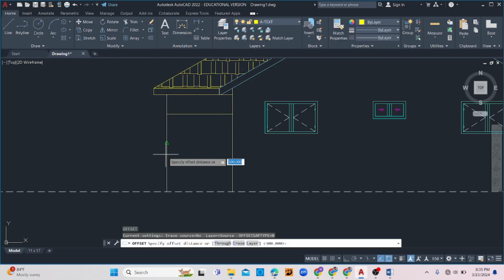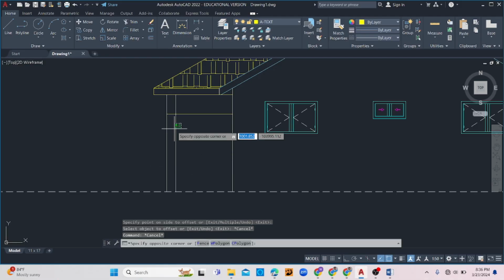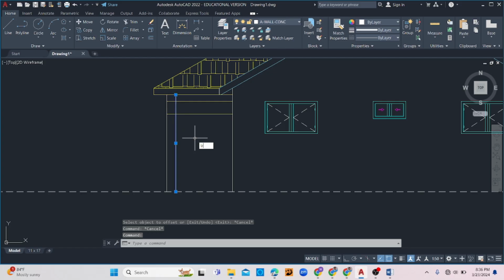However, I want to have a little column here. How much is going to be my column? I don't know at this time. Let's make it 8 inches, and 8 times 25 will give us about 200. So let's offset this line by 200. Now I can use this as my guide to generate my little arc for my opening archway.